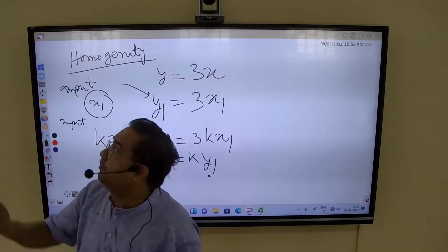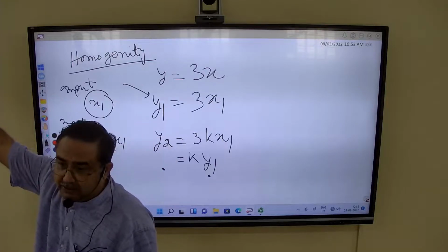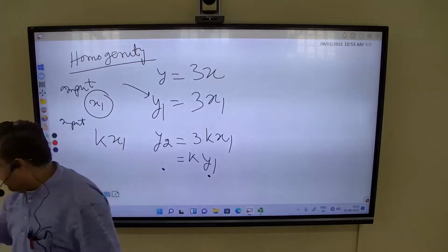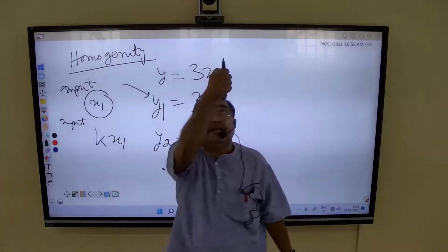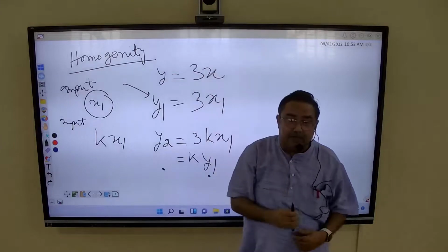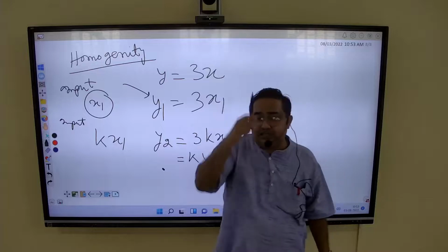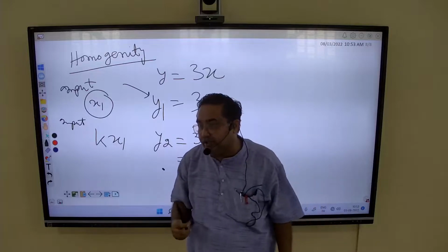I have to apply a strip over this initially when it is not in running condition, and then I can put my tachometer here, okay, and I can get what is the speed of that. I will explain you in the laboratory also. Is it clear? So without touching this, a non-contact tachometer is also there.